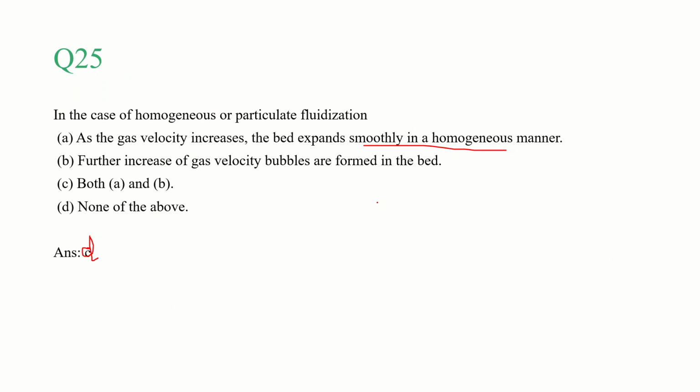with gas velocity actually. I mean, it is not associated with gas, because when gas is passed, it would be moving very fast. The chances that it is going fast is very strong. So it is not a homogeneous fluidization, rather it is heterogeneous fluidization with bubble formation and all. And since it is bubble formation, it is not homogeneous. So the answer is option D, none of the above.